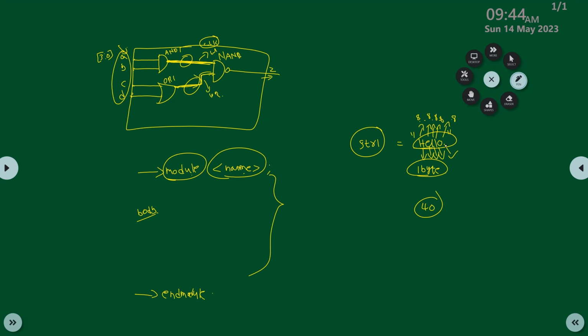So you need to declare str1 as a register, and before that, how many bits do you have to give? [39:0] str1. Then you can write str1 equal to hello. So this is the way to define small strings. Usually, we mostly won't use string notations and string initializations.